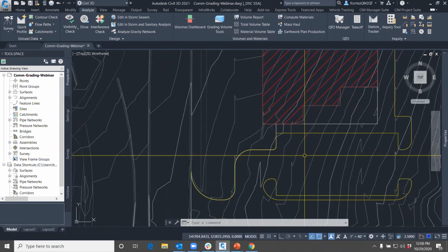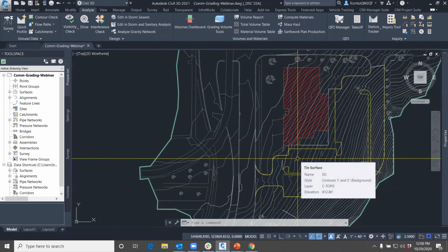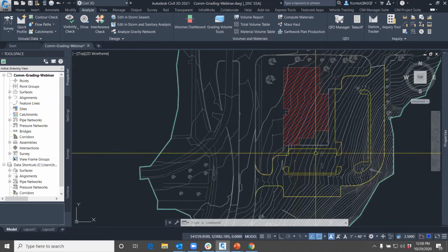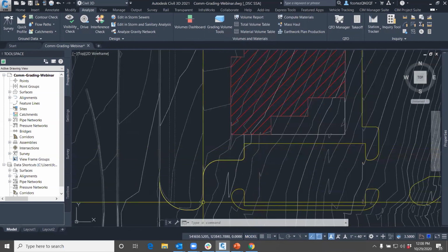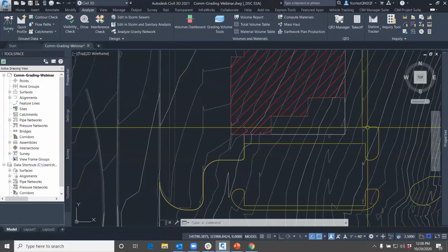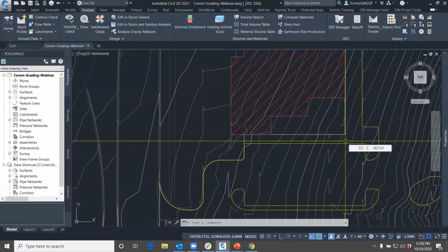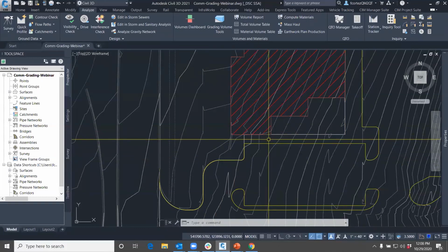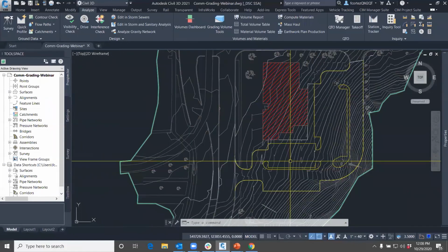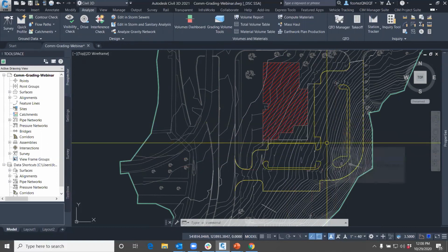That's another feature that has really made this workflow very efficient with the latest updates in Civil 3D, where you can have feature lines be dynamically linked to another surface. And with that all done, what we will then do is create our corridor that will wrap around all of our face of curb at our flow line, and it'll establish our top of curb, back of curb, and sidewalks in some cases. It'll create our islands. And not only that, once it's done, we can also create a second surface of our datum and pull earthwork.